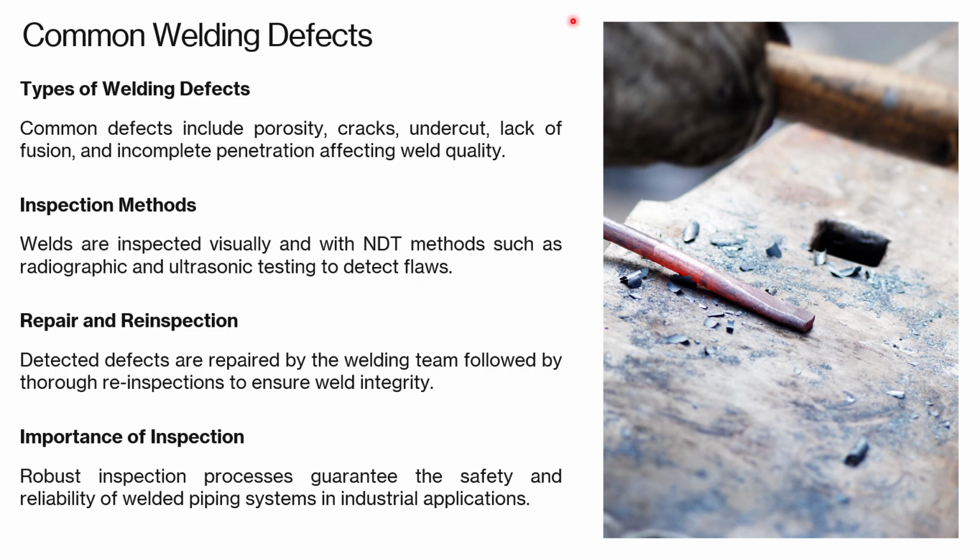Okay. So what do you check? You ensure that all welds are inspected visually. Visual inspection is the first inspection, and after that NDT processes such as radiography or ultrasonic testing should be done.